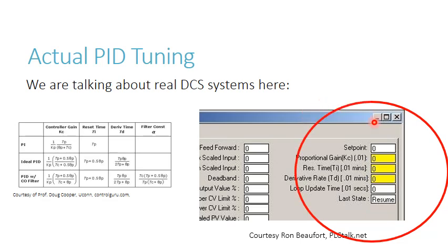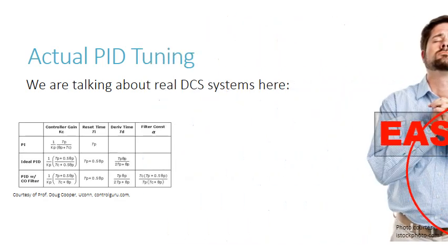And here's how it's really done. So you did your measurements, you found the gain and the time constant and the dead time, and you found those through your analysis in MS Paint or with a ruler. And then you did your computations on your calculator, and you plugged them in here in this nice Windows 98 GUI. Look at that. There's your proportional gain, your integral time, and your derivative time. There they are. You work them out here, you plug them in here, you press enter, and this Windows 98 program will send it to the Allen Bradley PLC-5, and that will implement your controller. That seems pretty easy to me.